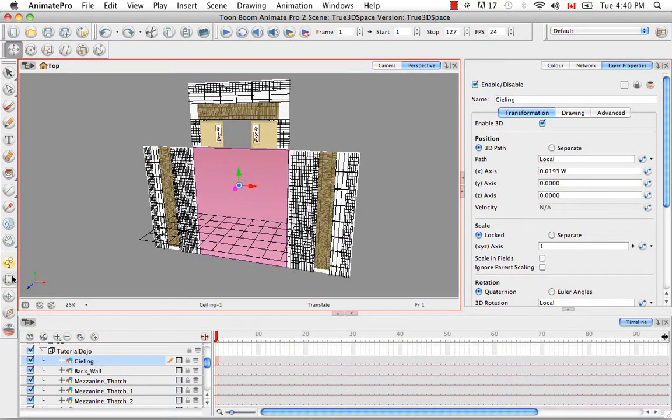So even though with the Transform tool, you'll see that you can pretty much drag anywhere, it's actually recommended to pull along planes. It becomes less confusing because sometimes when you're dragging in a random direction, you think you're going straight up or straight across parallel to the X or Y axes, but in fact, you've made a slight rotation as well. So it's recommended to go along straight angular paths, and actually it's recommended not to do any of these transformations I'm showing you in the perspective view. So I'll show you later on where we're going to actually do the movement.